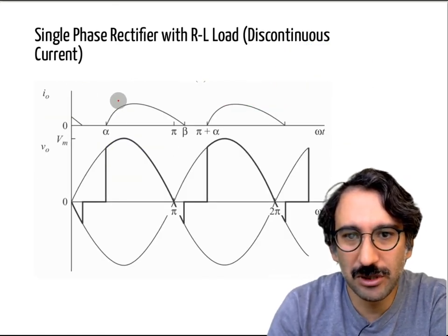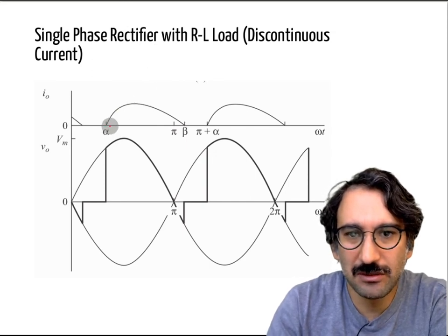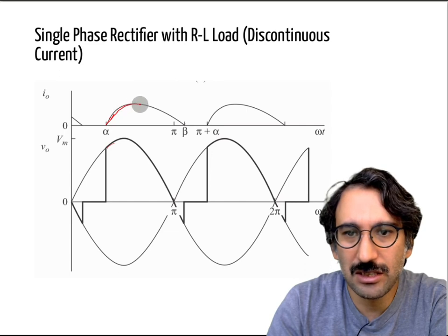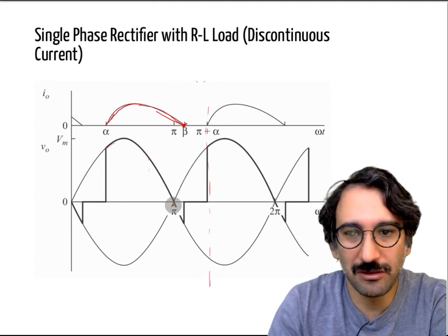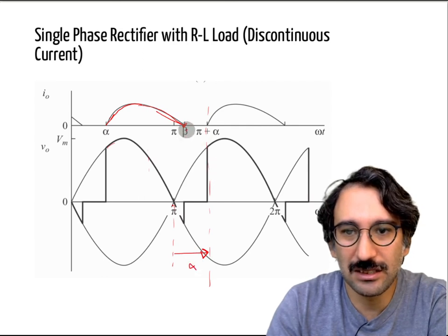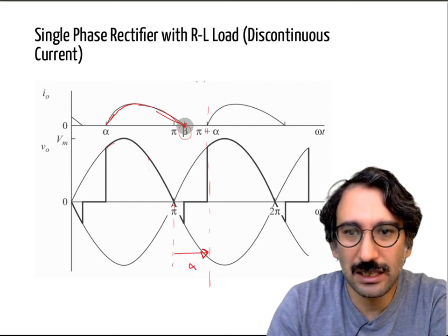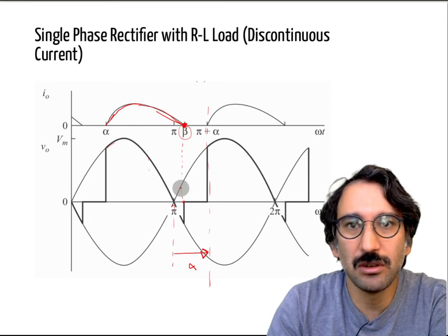It is similar to what we had with the resistive load. Yes, at that point you can start charging your RL load. At some point it will start discharging, and if you're firing, that happens after your firing, but let's say your firing angle is larger than that beta angle. So again, it is similar to resistive load. At that point your current reached zero, okay.